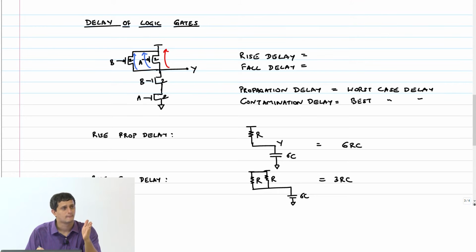So the bottom transistor, suppose that input was high for long enough and it has discharged that intermediate node X to ground already, right? Then the output Y needs to be pulled down to ground, that's all. As opposed to if the A input also had to discharge the node X to ground, then it's both these nodes that have to be discharged to ground at some point.